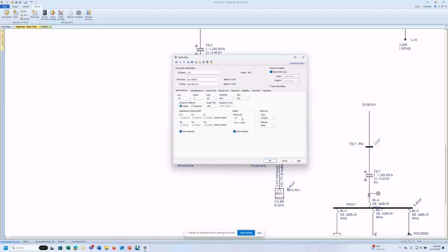If we want to derate this cable installation, we have to click on our Specifications 2 tab, where we see the ampacity derating section here, which is where we can select the common duct configurations. You'll see D1 through 4, D9, 10, and then the tray configurations. So if I imagine this is a D3 with 6 cable feeder conductors in a single conduit, we'll come back to our Specifications tab, and we can see that from 350 amps, this cable has now been derated to only be capable of carrying 214 amps. Similarly, we have also derated the terminations down to 189 amps.